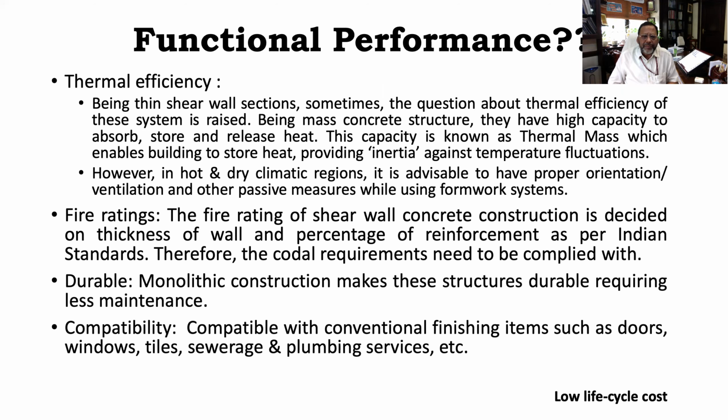So let me introduce the concept of thermal mass here. Because it is a mass concrete structure, it is primarily concrete. This mass concrete has a high capacity to absorb, store, and release heat. So it absorbs the heat and releases it slowly. This capacity is known as thermal mass, which enables the building to store heat, and because it stores and absorbs heat, it is a kind of inertia. It provides inertia to temperature fluctuations. So because of the thermal mass, the thermal efficiency is improved.